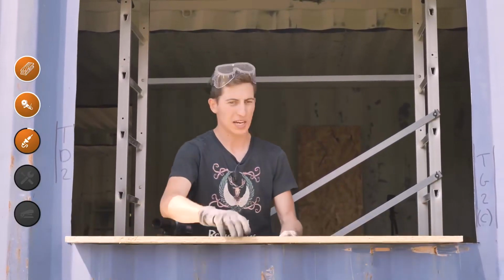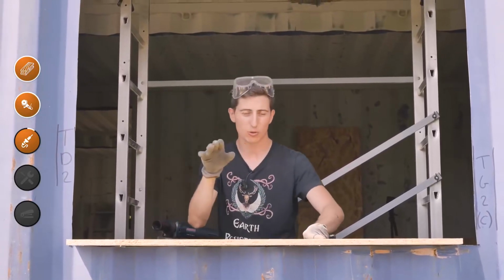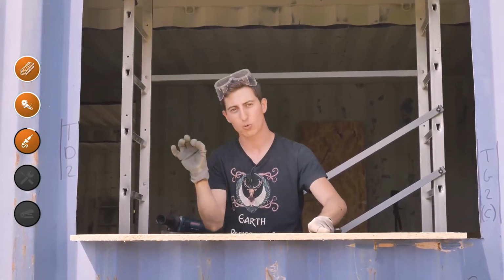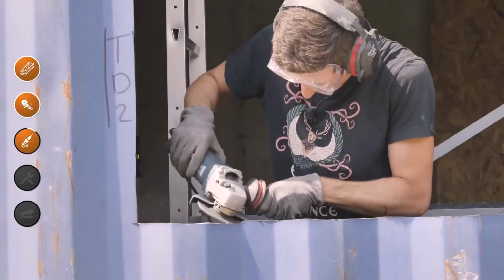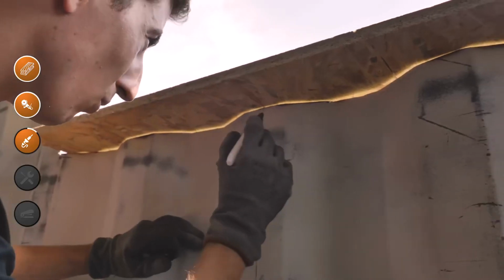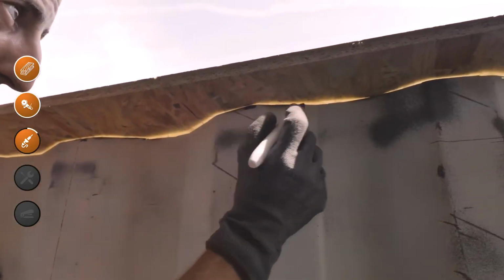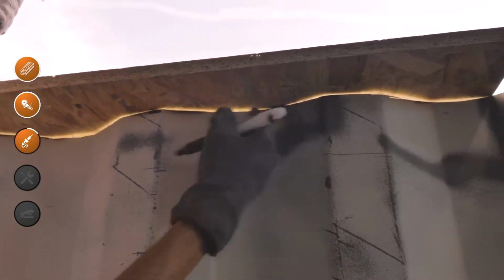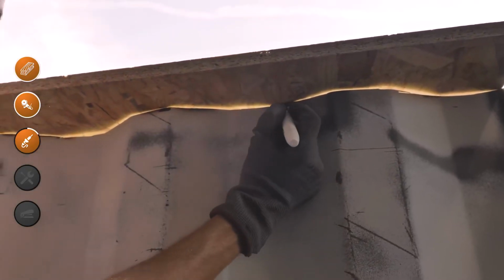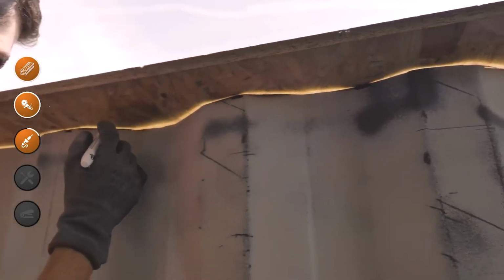I'll place a scrap oriented strand board piece and check underneath to see where my sheet metal touches or sits too high. I'll mark spots with a black pen and sand them again so my oriented strand board presses evenly on the sheet metal. You can see that here it's too much, here it's too much, here it touches. You see, here it touches, but here it doesn't touch. So I need to sand a bit more here and over there in the corner and then here.